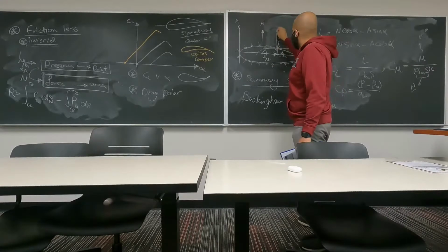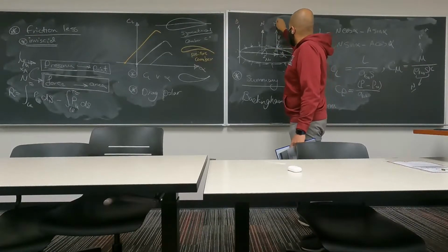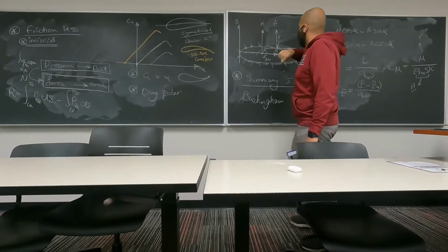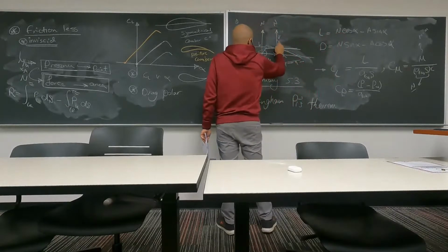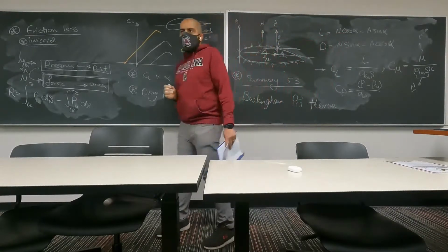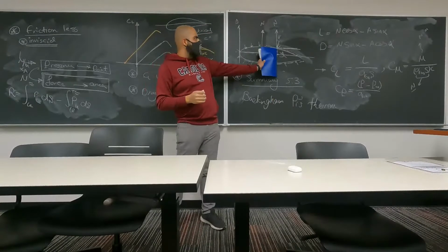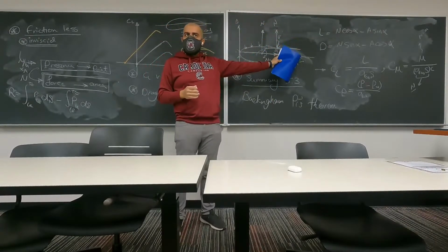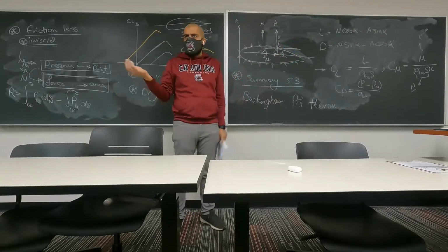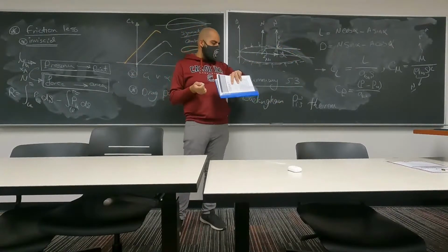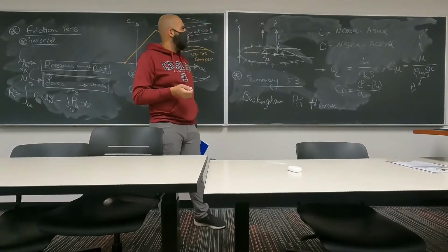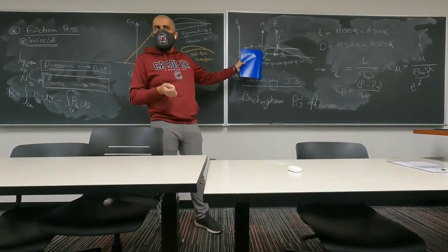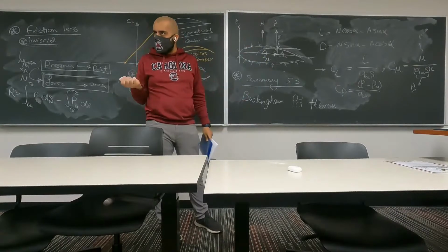Okay, so this is going to be the direction of the normal force, but this is the direction of pressure. So one component of pressure is contributing to your normal force. The other component is contributing to the axial force. Is this clear? What is the component that is contributing to normal force? It's P cosine of theta.